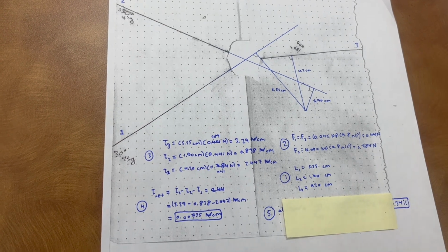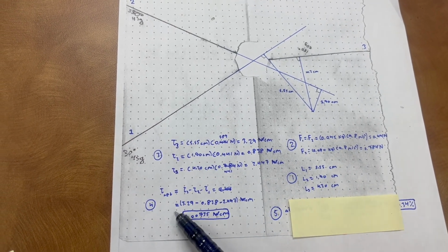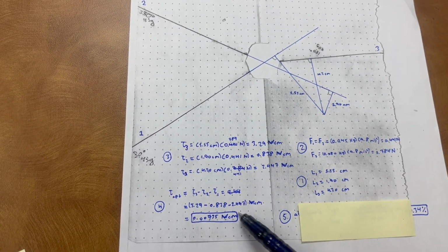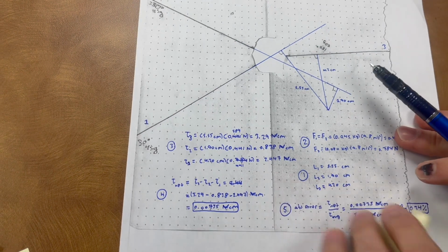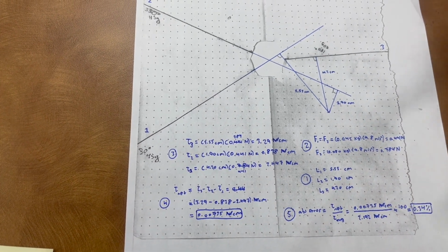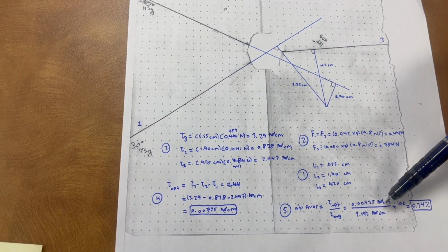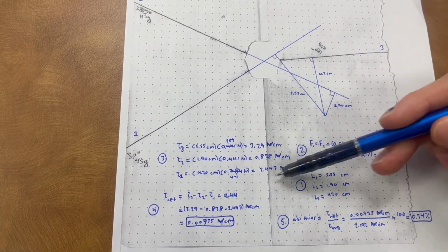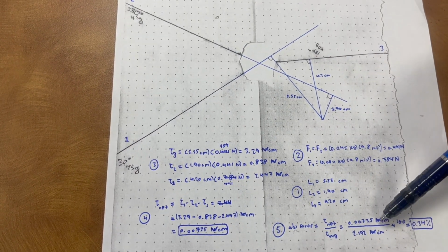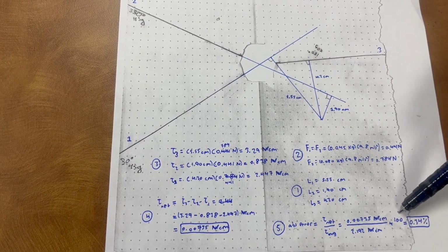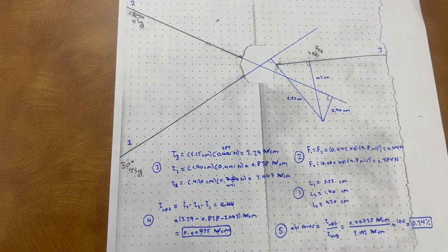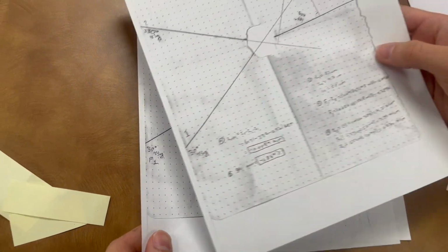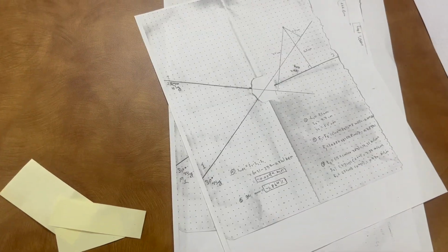This helps us when we calculate our net torque, because our net torque is going to be this torque subtracted by the other two torques. With this net torque, we can go on to calculate the absolute error, which would be our net torque, divided by the average torques, so these three torques added up, divided by 3. All of this multiplied by 100 to give our percent error. After you do this whole process, repeat it 2 more times to have a total of 3 data points.